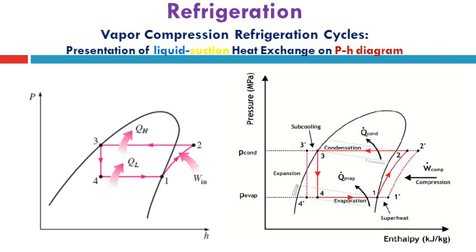The amount of heat must be balanced when using this liquid suction heat exchanger, and the effect on the COP must be studied carefully before taking into account this superheat and subcooling during the design of the refrigeration cycle.